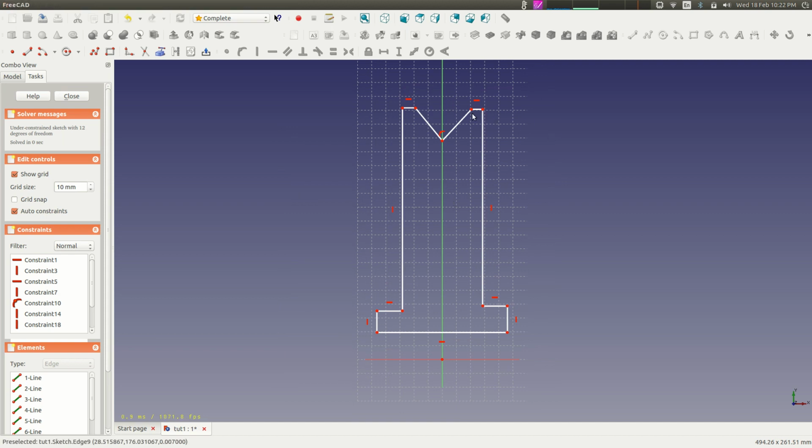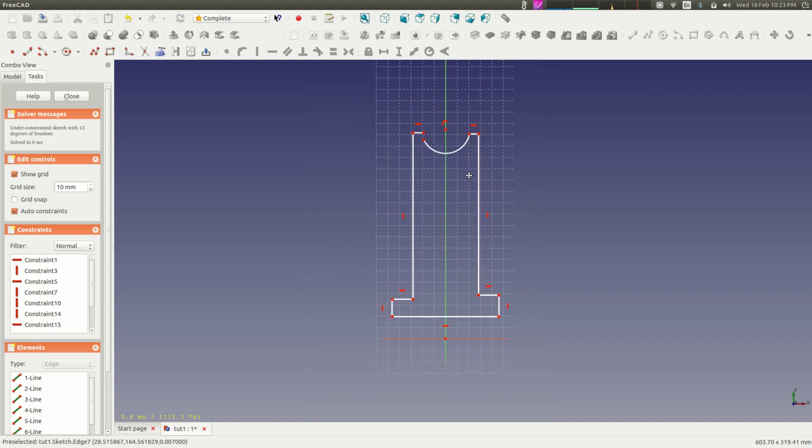So in my pulley, we have a circular arc here instead of a V cut. So I'm going to go ahead and delete these lines here, and we're going to make a circular cutout here. You can either use the circle tool, make a circle there, and then maybe cut one of the sides off, or you can use the arc tool, which is a lot nicer. I'd recommend that. And I want it to be centered on here. So I click where the center is, and then I can draw my arc like so. And so that's nicer there.